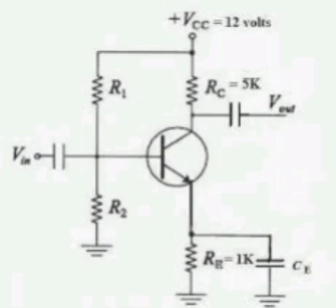Reading of voltmeter 1, V1 equal to 150 into R dash by R dash plus 100 kilo ohms. R dash equal to 50 kilo ohms parallel with RV1, that equal 50 kilo ohms parallel with 50 kilo ohms, 25 kilo ohms. V1 equal to 150 into 25 by 25 plus 100, that equal to 30 volts. Using voltmeter 2, same.